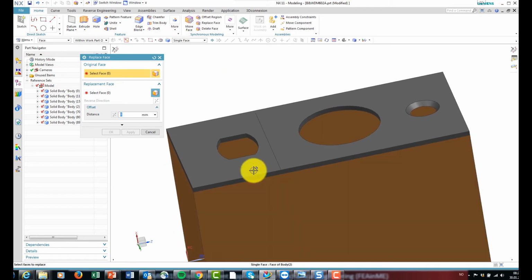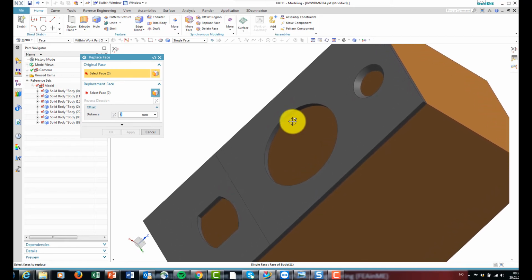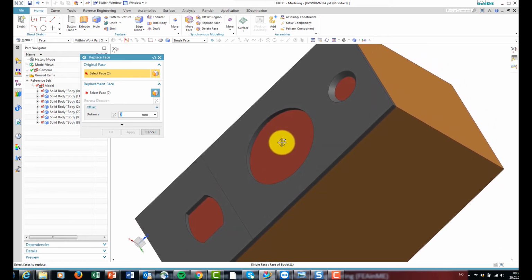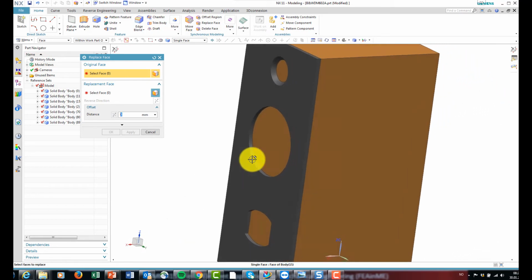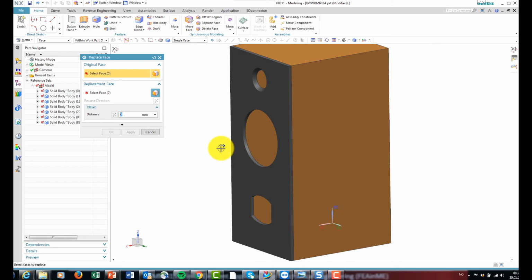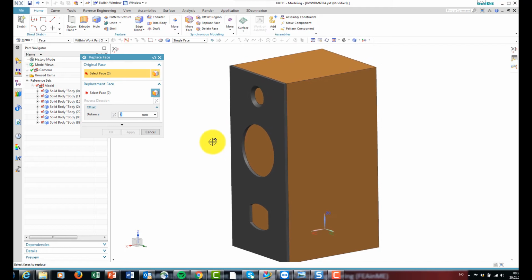Now I can easily add ribs and change the thickness of plates, and it's easy to update the mesh and check the consequences of the changes I've made. And as you know, the objective with this exercise is to prepare a loudspeaker for modal analysis. So small features are not of great importance.